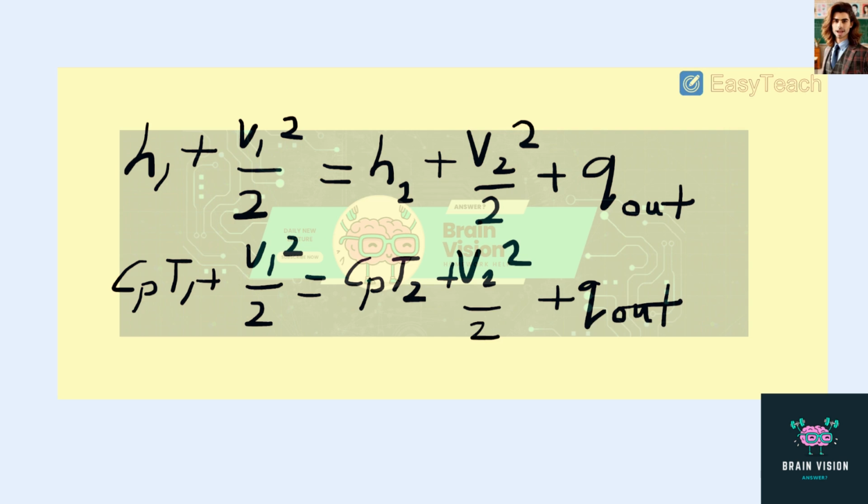Now what we're going to do is assume that the inlet diameter is going to be 1.4 meters and the exit diameter to be 1 meter. Recall that we had a relation relating these inlet and exit diameter ratios to be 1.4. So I'm going to plug that into our mass balance equation, and that's going to look like this.